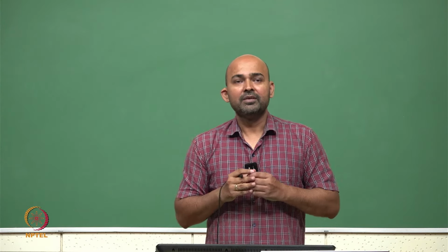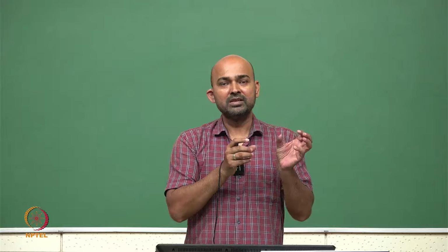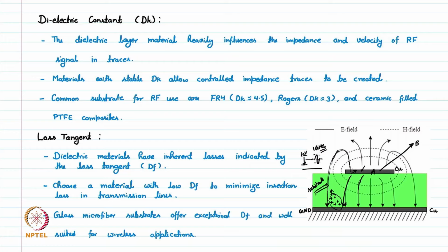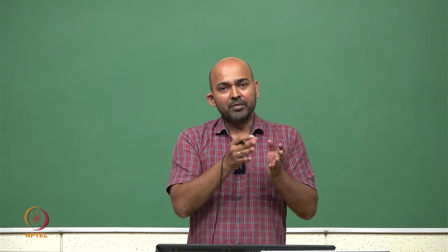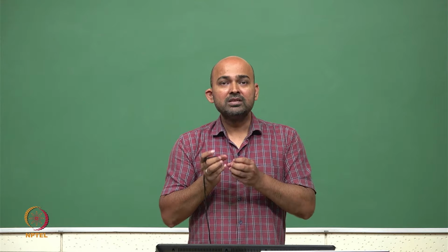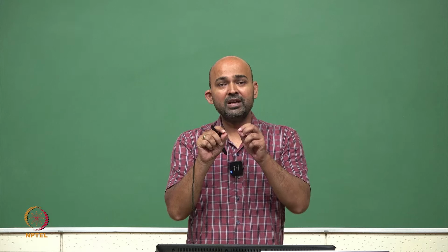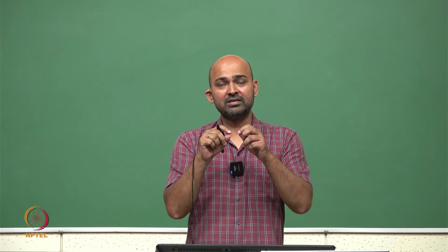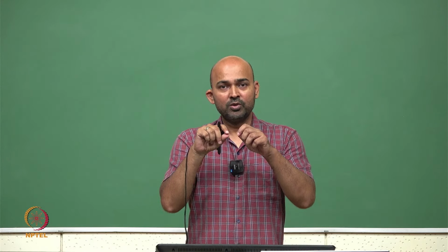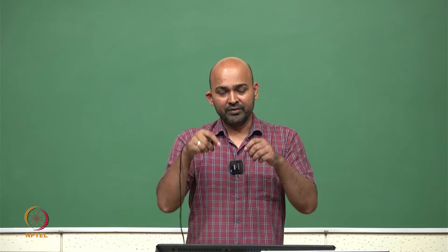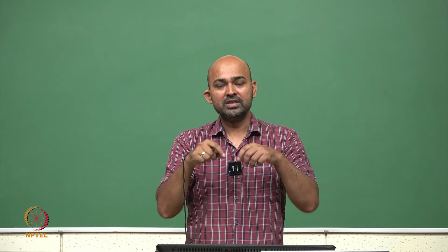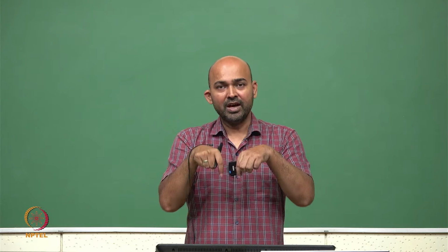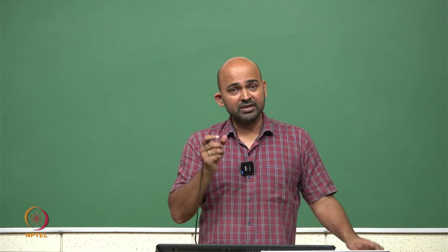For example, we are using a 100 ohm resistance in our schematic. Now we have multiple options of putting this 100 ohm on the PCB. We can go for a big resistance which is a through hole component, where 2 lead wires come out and we dig 2 holes in the PCB. We put these lead wires into that and solder it. This is one way.